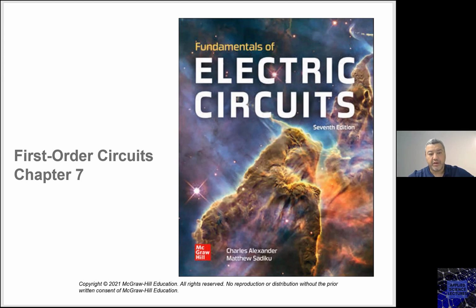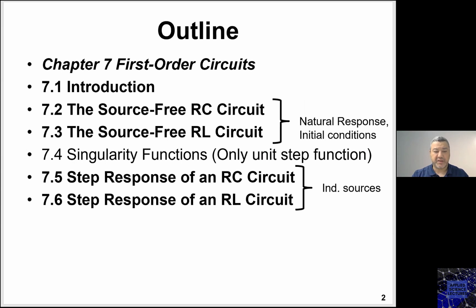Today we will be looking at a new topic. This topic is called first order circuits. In first order circuits, we'll be dealing with transient responses, as we will see later on, for circuits that are source free. What does source free mean? It means that there are no independent sources to drive those circuits.